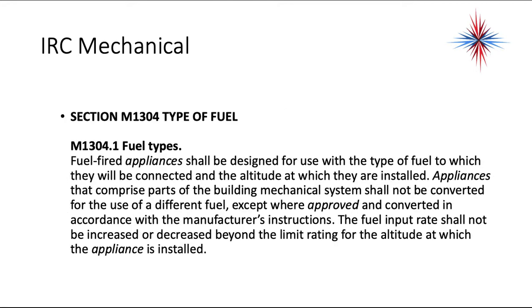1304 determines the type of fuel that's allowed. Fuel-fired appliances should be designed for the use of the type of fuel which they'll be connected to at the altitude where they're applied. Appliances that comprise parts of the building's mechanical systems shall not be converted to use a different type of fuel except where approved and converted in accordance with the manufacturer's instructions.